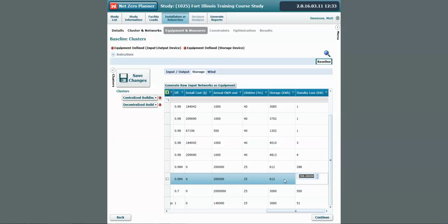That idea is very different for networks, centralized networks, and distributed equipment. So if we're working with a building cluster of 10 buildings that are on a network, that's going to be a very small network. If we're working with a building cluster of 150 buildings, it could be a very large network. We've seen systems of around both of those sizes, and so we need to do specific calculations to determine the size, the amount of energy lost, and the costs related to those systems.